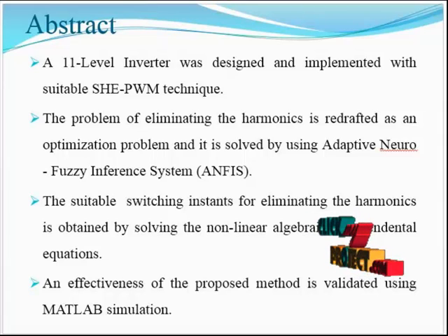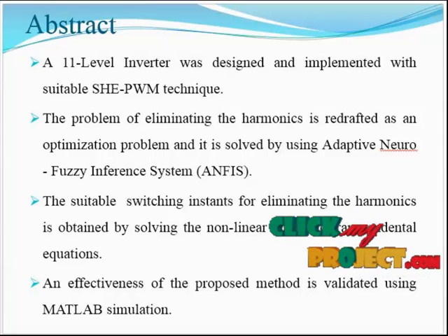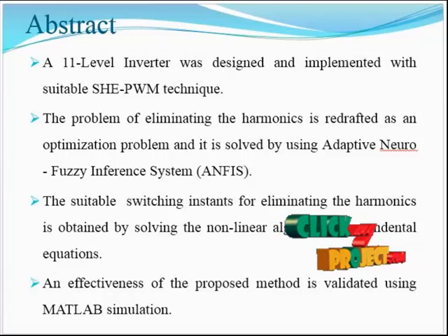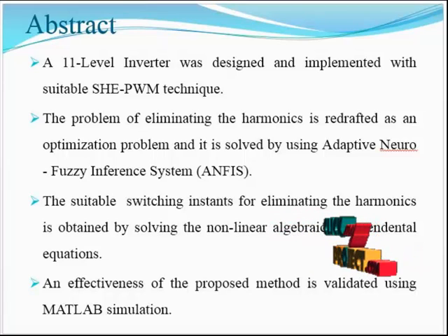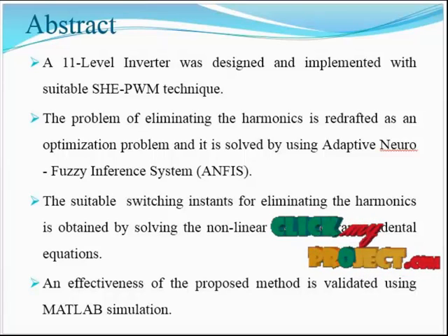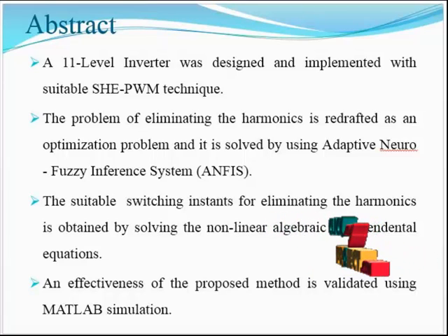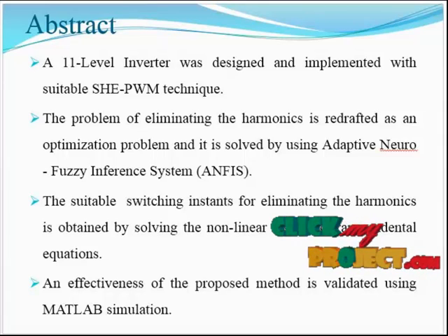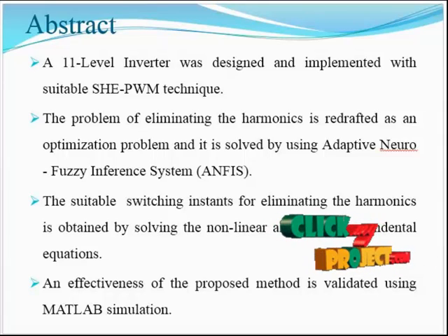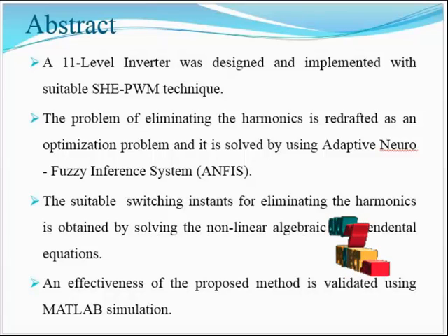How are these equations formed? The inverter output voltage is represented as a Fourier series expression. This expression is called a set of nonlinear transcendental equations. The solution of these equations corresponds to the switching instances required for the problem. The problem here is redrafted as an optimization problem.